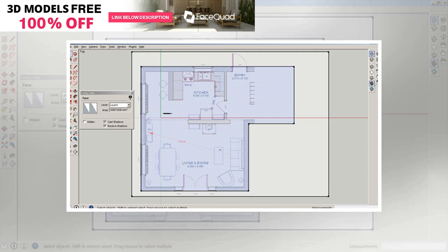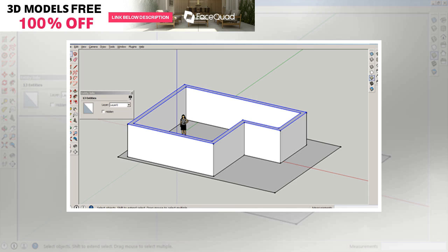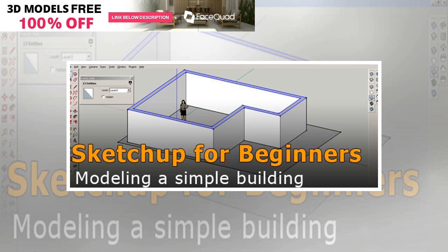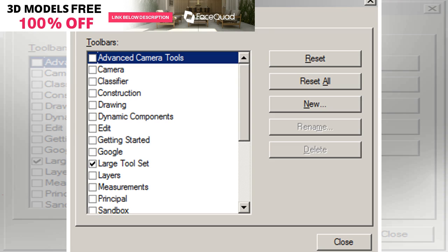You probably have floor plans of your house, either made by an architect or hand-drawn by you. Depending on the format of those drawings, JPG, PNG, PDF, DWG/DXF etc., the following procedure may change a little bit. Let's consider raster graphics formats first, as it's the most common case that moreover requires some additional work in comparison to CAD formats like DWG/DXF. Use the drag and drop method to place the file with the floor plan into SketchUp. Find the list of supported formats on the figure above. Alternatively, you can use the import dialog under the menu File.